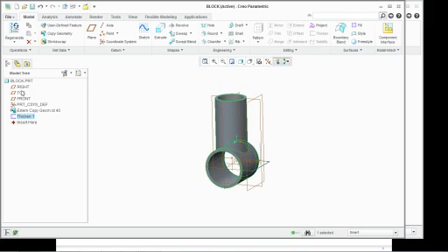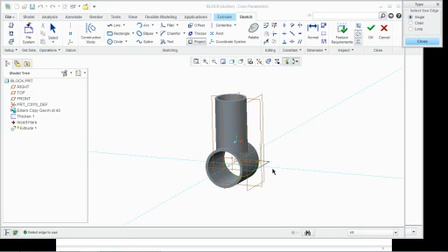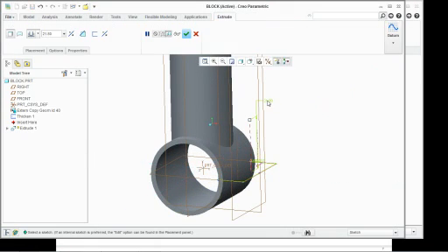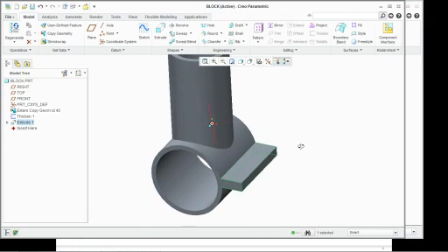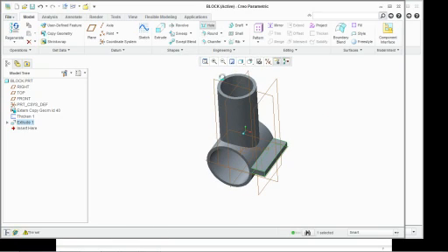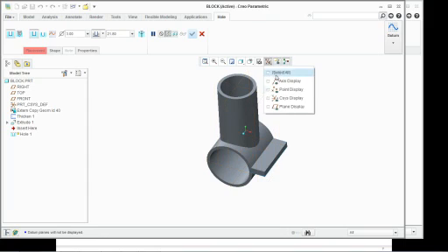I also want to go in and pick my top plane, say extrude, use my project and select loop and pick this edge right here. Click close, click OK. Set the thickness of this to 4. And I want to come in and add some holes in here. So let's turn off our planes. They're getting in the way now. So I'm going to leave my axes on.